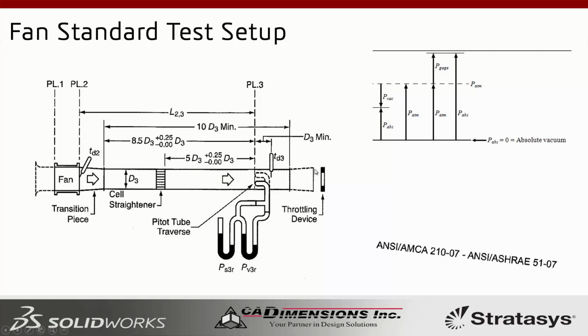So it doesn't completely close it, so it allows some air to flow out, but what that does is increase the gauge pressure, or the pressure buildup, in the system. You will see that as this throttling device moves back and forth, the air pressure and the velocity change as well. So the pitot tube right here allows you to ensure that your throttling device is in the right location.